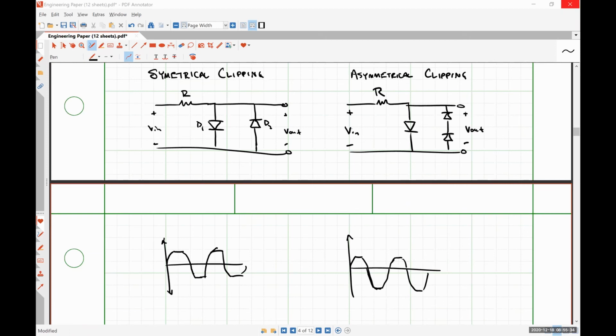All right, the general design process is to follow these steps. Identify the general requirement of the circuit. So what are you actually being asked to do, which is usually specified extremely well in the project descriptions. If you don't feel that you have enough information, look at other things, research the topics, or feel free to ask me a question. What is required of you is to formally compile a list of the figures of merit and secondary requirements, such as size and power requirements, and spend some time analyzing the priority.